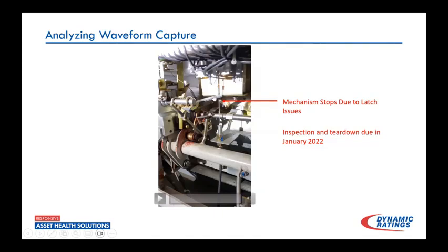We will see this arm will start to fall. And then this is our main cam, and this is where our main contacts are attached to. When this first initiates, this moves a little, but then this stalls. And so we're not able to release that stored energy immediately. We sort of let a little pressure off those contacts, and then once that latch clears totally, now we see a full open.